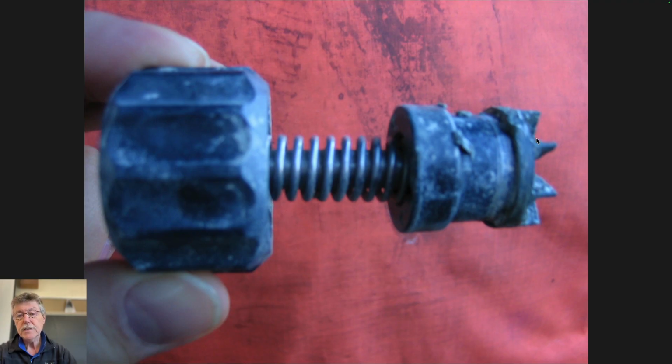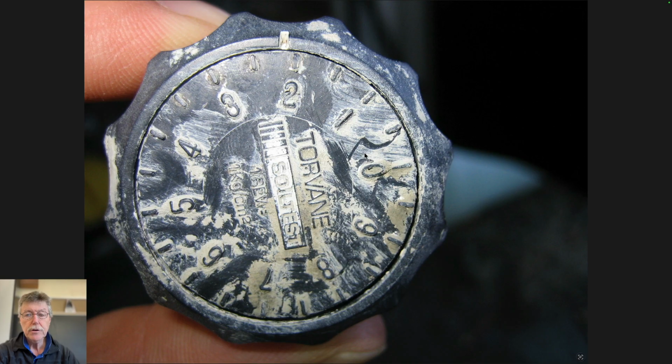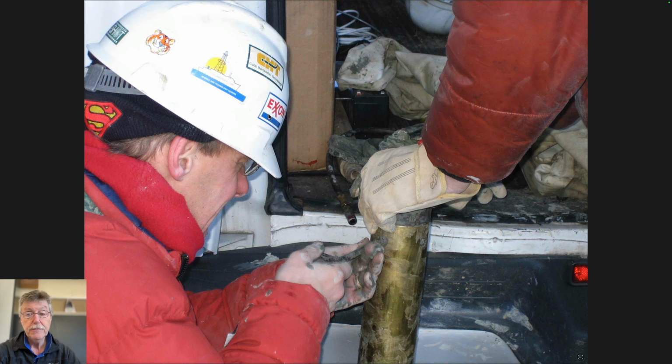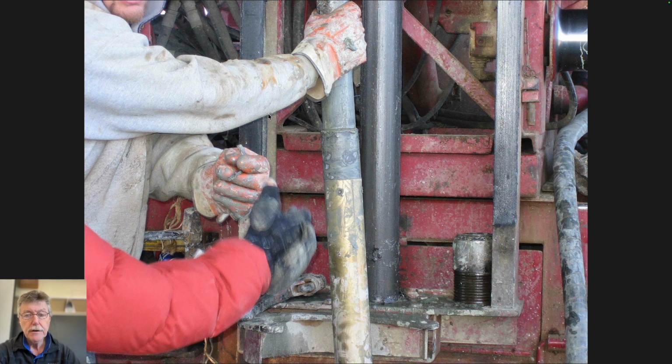So you have this little ratchet here. These little fins get pushed into the end of the sample. It's on a spring, so not to compress it, a spring which acts as a torque wrench. And so you turn it, and as soon as it reaches a particular torque, this will fail, and it will record that torque magnitude on the scale here, and it gives you an impromptu strength of the soil if you need that. Not really for the things we're talking about, but you do for foundation engineering stuff.